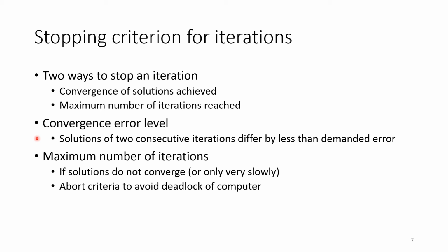Now you could say, well, I could just use the maximum number of iterations, because if it converges, that's okay to me, and if it does not converge, it will abort at that maximum number anyway. However, through the convergence level you are usually faster, because if the solution converges, you reach the level of convergence earlier than the maximum number of iterations, usually substantially earlier.